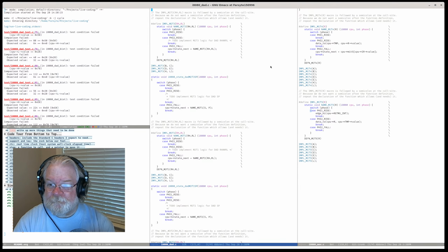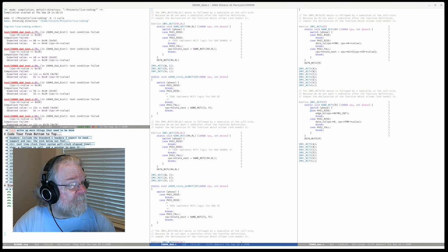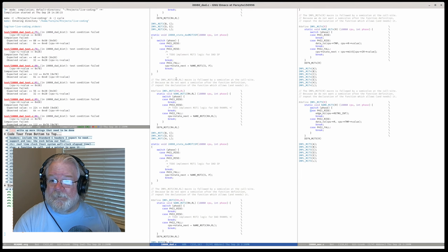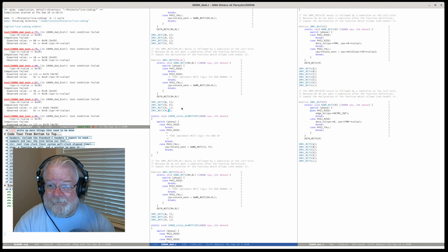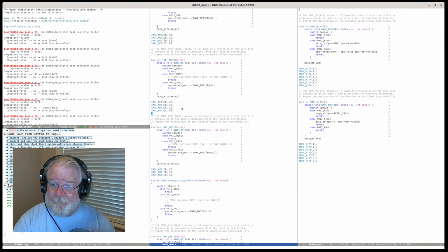Okay, M2T3. Back to the timing diagram on the right. I keep this far to the right on another screen so I can see it. It's not useful enough to have it here. So M2T3, we are taking the ALU content and writing it to the L register and to carry. M2T3 also does not need a customized version for the SP because we're done dealing with SP until the next cycle.